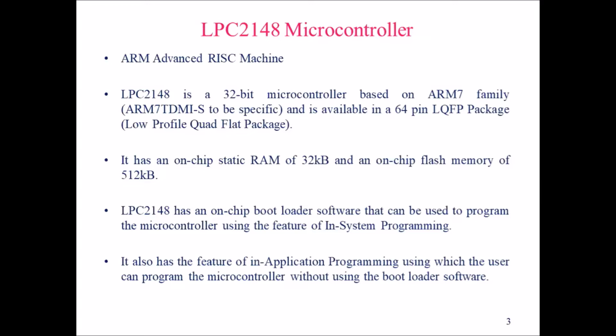It also has the feature of in-application programming, using which the user can program the microcontroller without the bootloader software, by using a Windows software or Keil IDE to implement the program, compile it, and dump it to the microcontroller to execute. That is what in-application programming means.